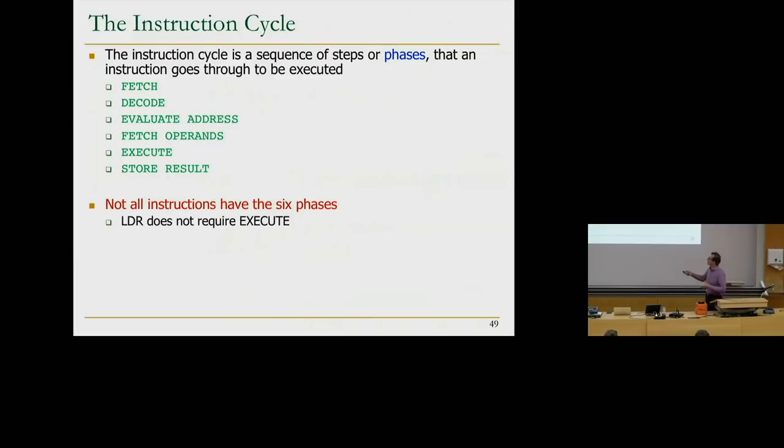For example, if you saw the load earlier, base plus offset, it's called LDR, load register. It doesn't execute because there's nothing to execute. You're just loading some data value from memory into a register, right? You don't go through the ALU, the arithmetic logic unit.